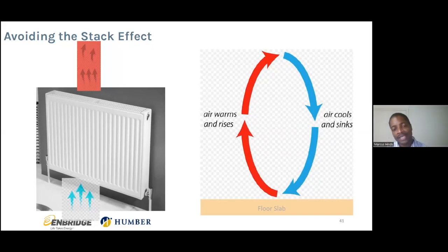Right? So as your radiator is giving off heat from that hot water, the air around it is going to rise, right? And it's going to be drawing cooler air to the bottom of it so that that air can rise constantly. And that's what we call the stack effect. If it's somehow hindered, it's not going to be as efficient as it possibly can be.